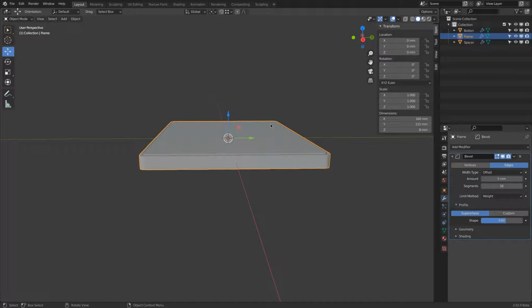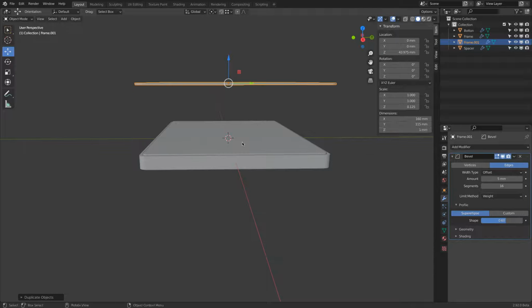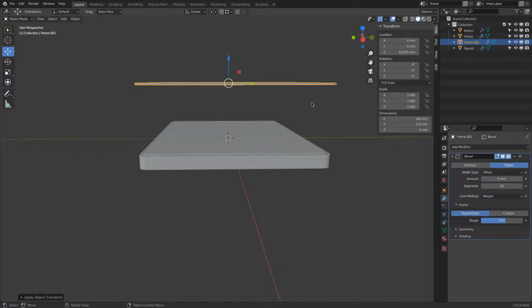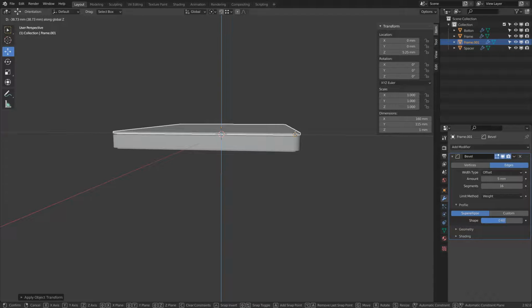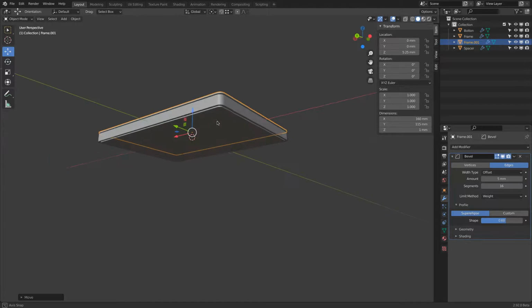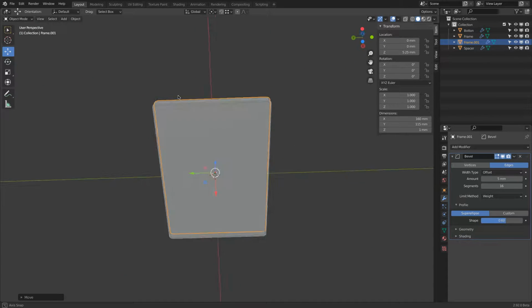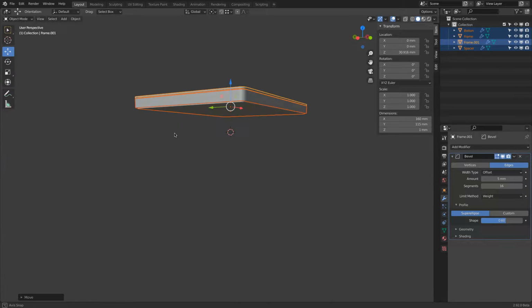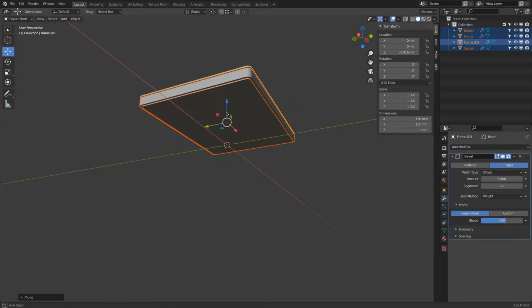maybe spacer. And now I need the touch surface. I select my frame, Shift D and Z, 1 millimeter, Q, and apply scale, or object apply scale. GZ, hold Control, and be careful where we snap to. There we are. Pretty cool. Nice. Let's select everything, A, and then GZ. Move this up a little bit, because we don't want things to be right on the ground too.